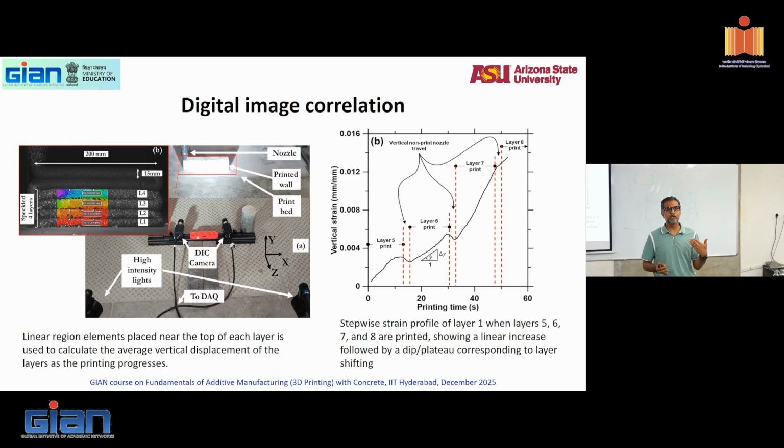So you don't ask me what is the internal strain, same as the external strain. We would like to think all of those strains are the same. They're essentially not, but at least you can get the surface measure. And in places where you can't go and put in a strain gauge right inside the material, it's a very good approximation. Your wet concrete surface is very dark, right? So you need to have some bright speckles to give you contrast to see how the points move. So we have some white paints. I think it was a little involved process of doing this. You can talk to Abhinaya to figure out how he managed this.